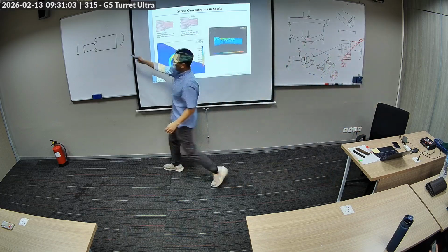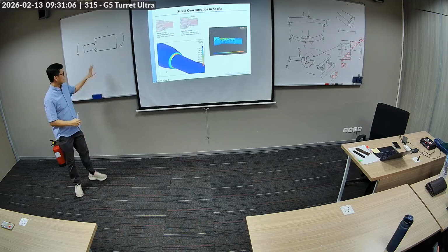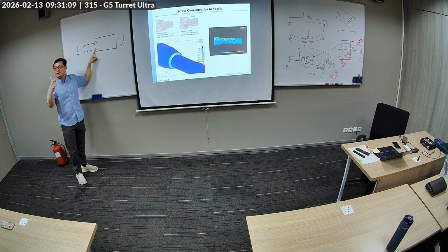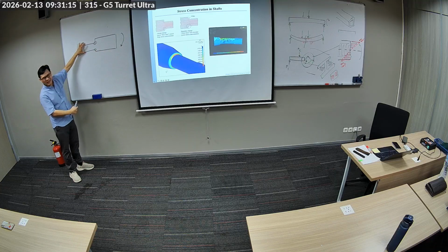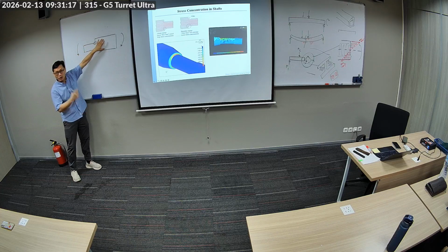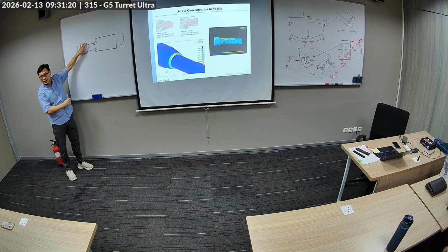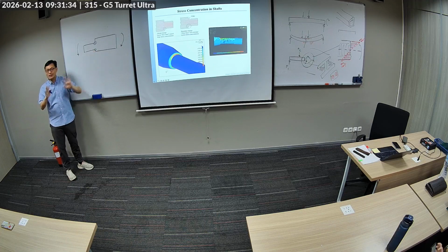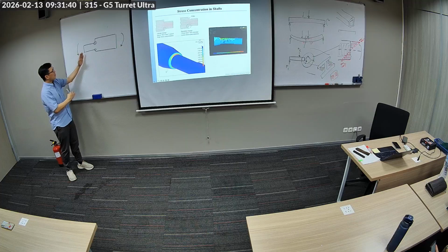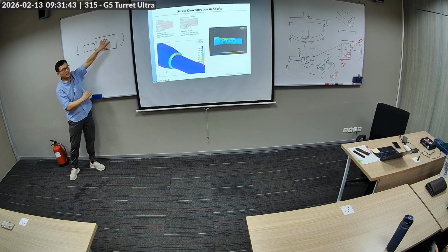So it's not going to fail here because the stress at this point will be multiple times the stresses everywhere else. So even though this is a small diameter, you will think, hey, this is weaker than that. So you will say, okay, it's going to break here. Yes, if this is not there. But because of this sharp corner, this is experiencing 3 to 4 times the stress. That's the kind of multiplication factor we're talking about. Not 10%, not 15%, but 200%, 300%. So that's why I'm not worried about this, and I'm not worried about this.